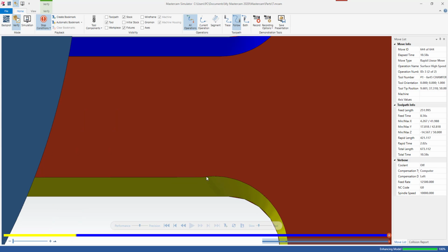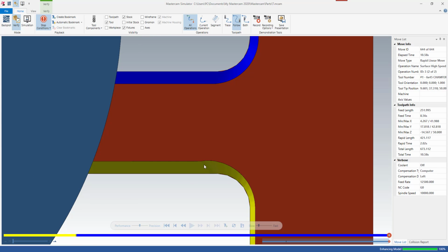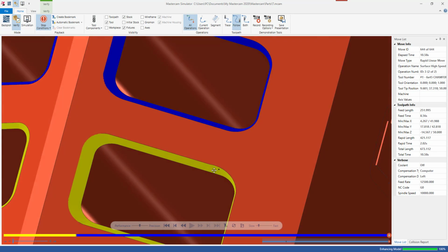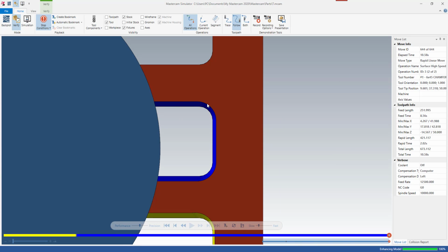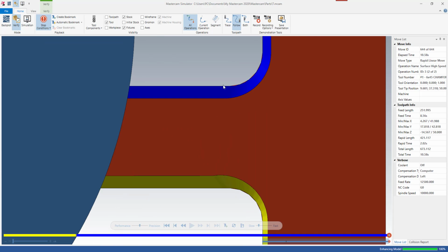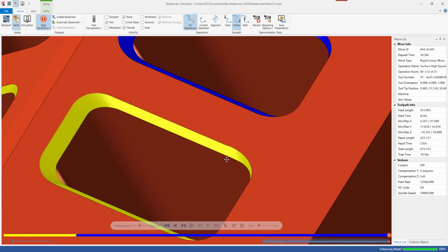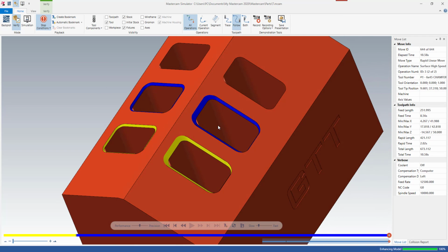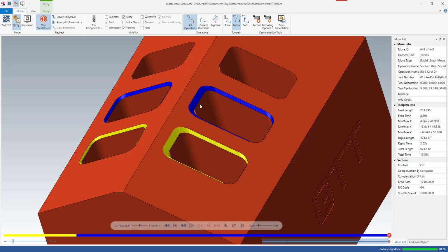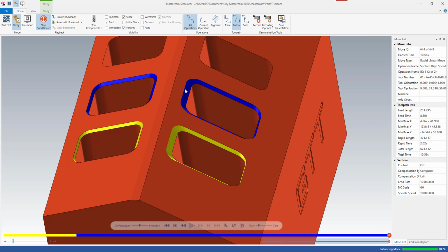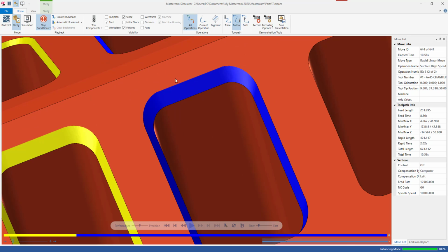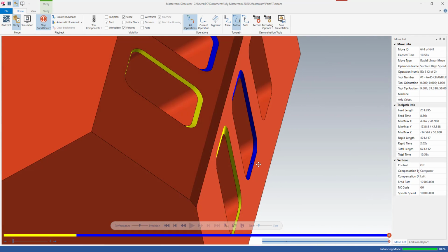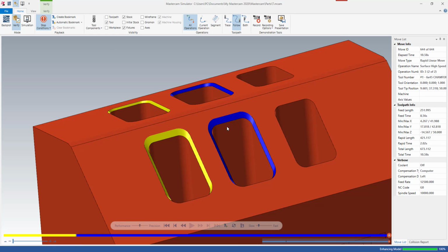You can see here in this area we have a transition for the 3D chamfer. We have something like a gouging, but we have a smooth transition here for the project toolpath. You can see this is smooth, and you can see we have a small gouging. Yeah, it's not so good. But if we talk about the chamfer, the Y of the chamfer is the same when we compare the toolpaths. The 3D chamfer and the project, they are the same results. We still have a big chamfer here and a small chamfer here. So that's what we don't like, what we don't want.